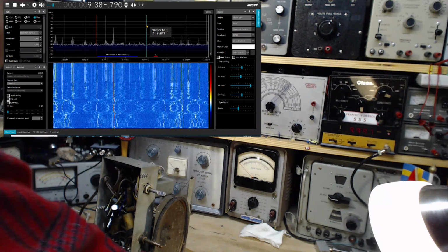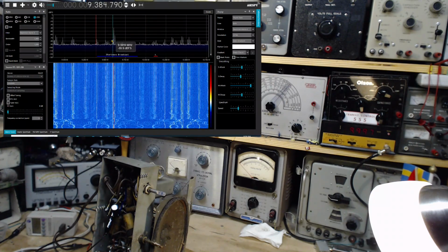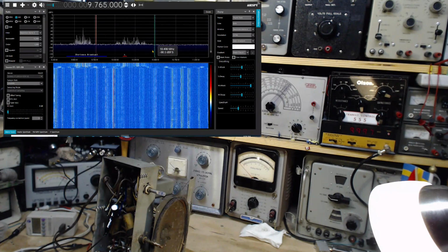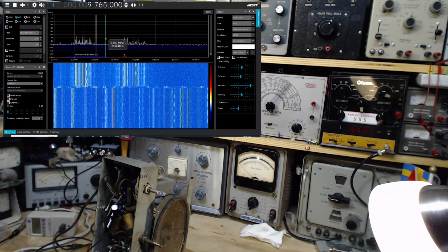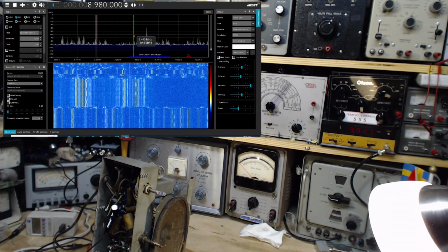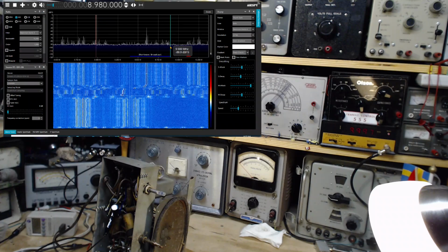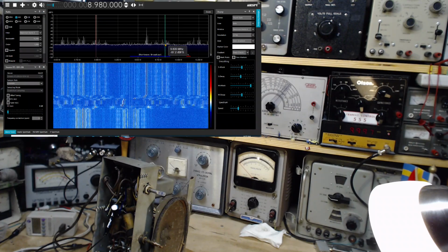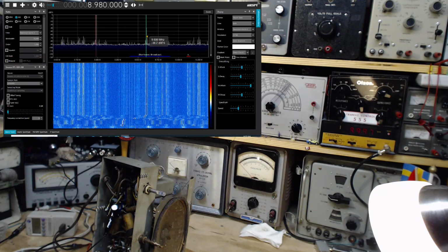So right now the local oscillator's got to be, let's look. It's either got to be here, 10, 455. I don't see anything there at all. Or it's got to be down below at 9. There's nothing here. 9.455 should be here. Right here. This is it here.